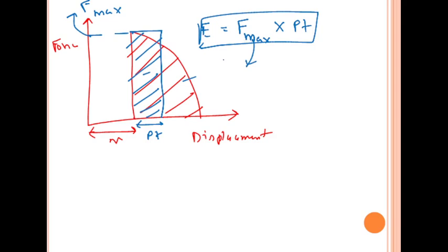So how can we reduce this? We can reduce the force that is required for the punching operation by shearing the punch. That is, by shearing the punch at a particular angle, we can reduce the force required. Now without shearing, the force versus displacement curve is a rectangle, but with shearing we will obtain a trapezoidal force versus displacement curve, which we will see right now. Wait a second, let me add a few slides first. Okay, we are good to go.